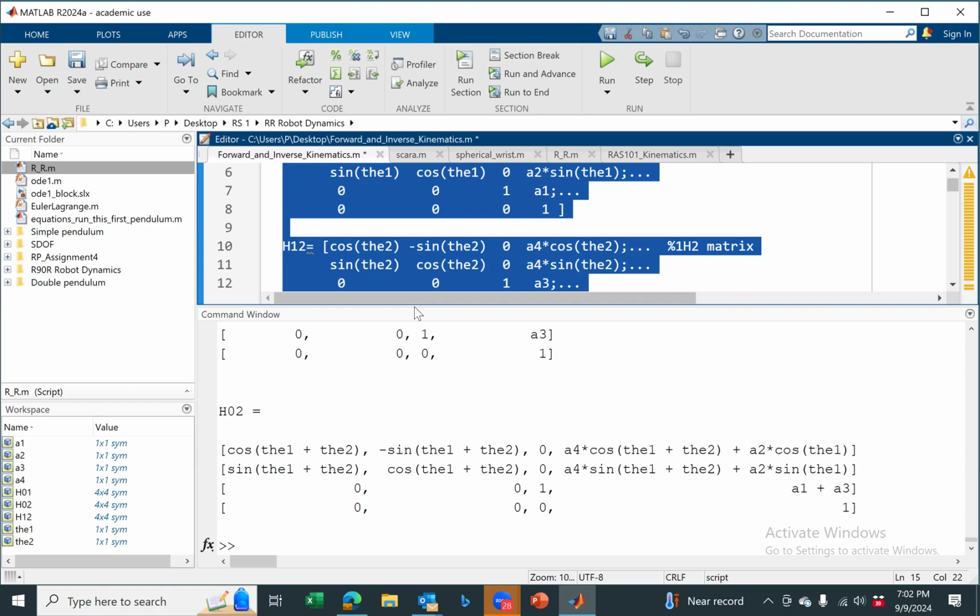So which means the forward kinematics gives me, as soon as I capture the homogeneous transformation, the rotational information, how far the end effector is rotated. Once again, this is the two-dimension, it's a pendulum, theta 1, theta 2. So overall rotation is theta 1 plus theta 2. Are you with me?